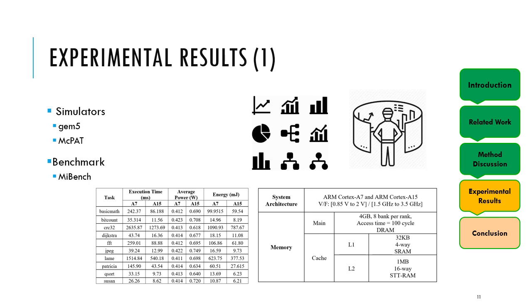As shown in the right table, we considered the ARM-based platform and used ARM Cortex-A7 and ARM Cortex-A15 as widely used cores in the embedded system to evaluate our proposed methods. So we suppose that our system is equipped with DVFS and DPM techniques. Then when it is needed, we can use these techniques to manage power and energy consumption.